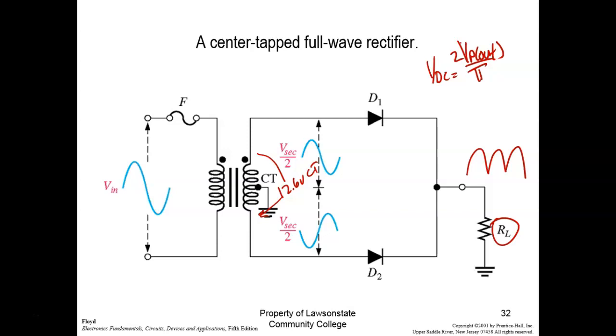So what I'm going to do first of all is calculate V peak. We're only using 1/2 of the transformer, so V peak secondary is going to be 6.3 divided by 0.707. Anybody do that? Why are we using 6.3 instead of 12.6? Because we're only using 1/2 of the transformer at any one time. That gives 8.9. Okay, so that's 8.9. Are we okay so far?